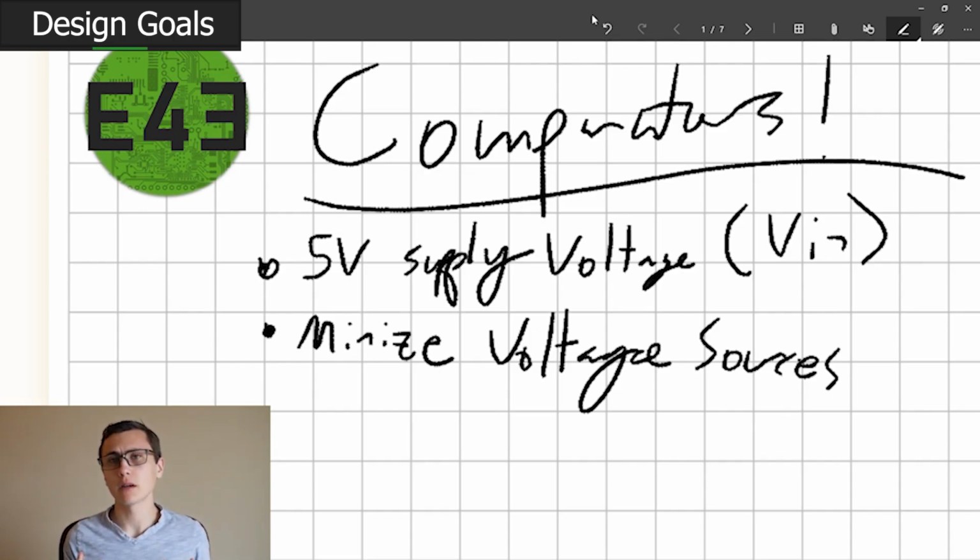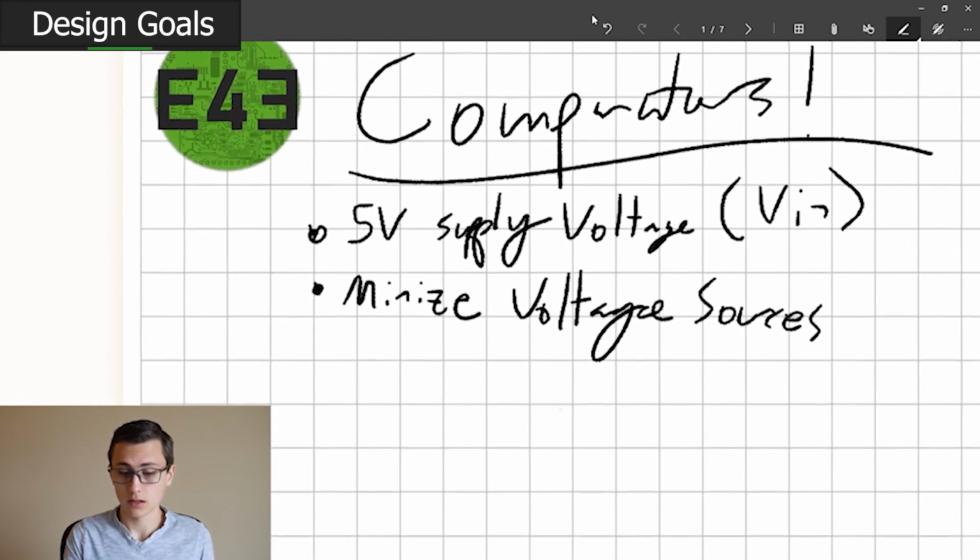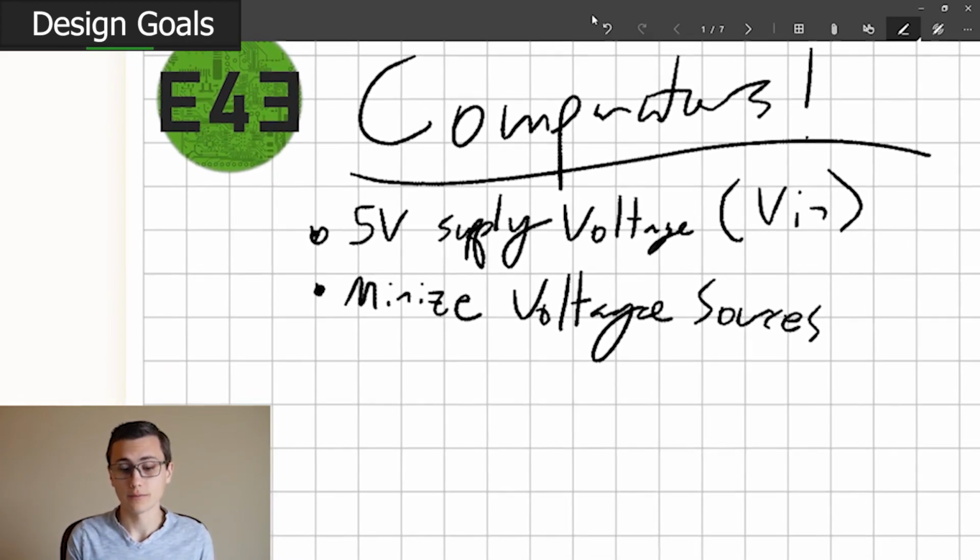That means that we might be giving up some accuracy or maybe some precision, perhaps both, but we don't need it. Not for this. This was coming back to our thermal runaway monitor, where we want to know the difference between normal operation and burning your house down. We don't need laser precision. We don't need a super accurate threshold. We just need to know that it will trip within some bounded tolerance range that will be safe. Okay? That's where we're going.